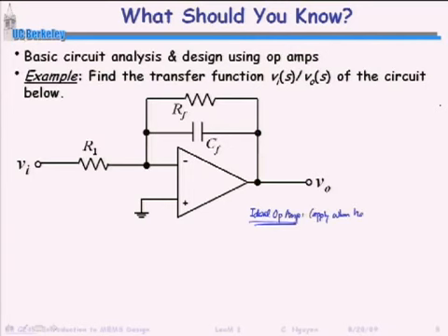Okay, so what are those properties? Go ahead. The current into the minus and plus terminals is 0. Excellent, yes. I have that as number 2 in my notes, so I'll put it there. So that basically means that the input resistance, Rn, is infinity. If I look into this node of the op-amp, that resistance is infinite, if it's an ideal op-amp. Okay? What else?